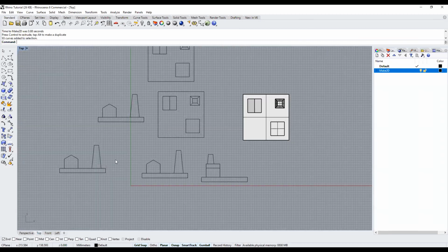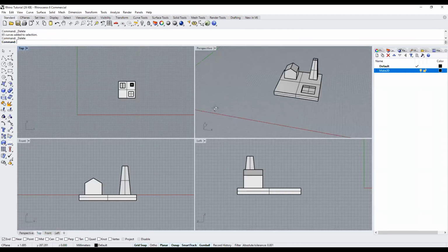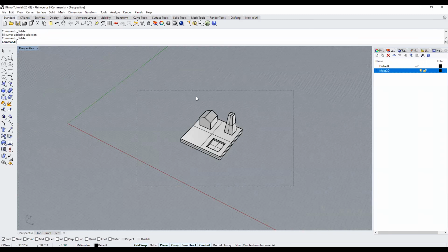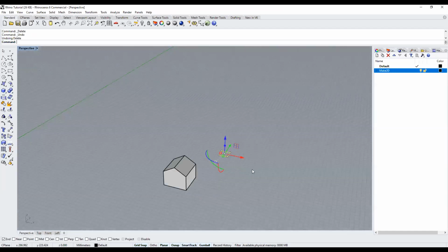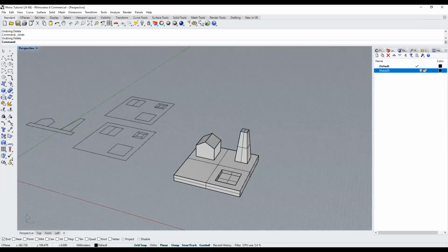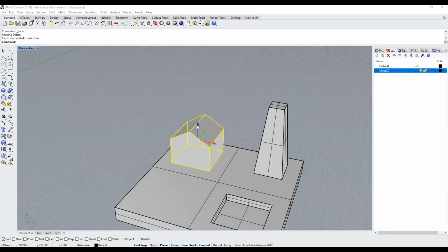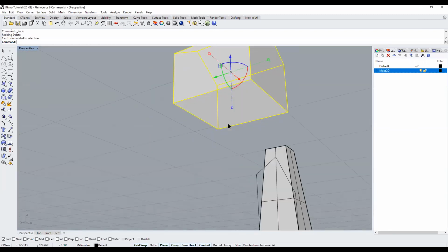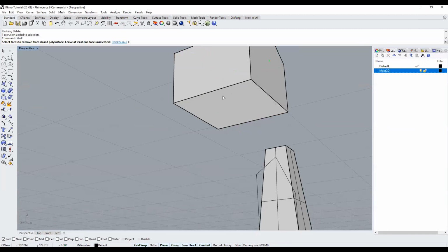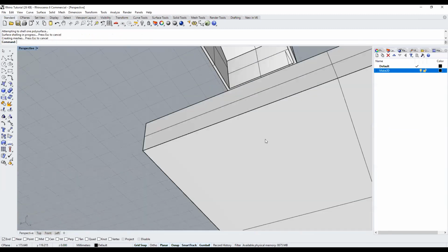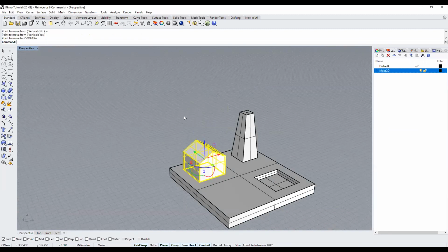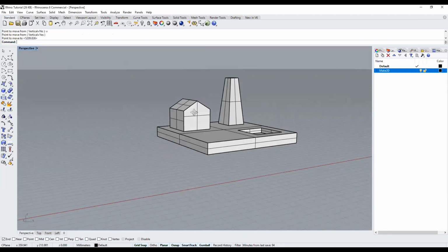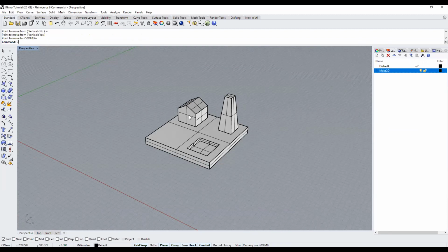As for sections, since these are volumes, I think I'll create a shape better for it, something with more thickness. I'm just going to make this hollow inside. So now you have a thickness for this wall. I want to move it back, move vertical, bring it back down. To make a section, there's another command you need to know, and that is called clipping plane.